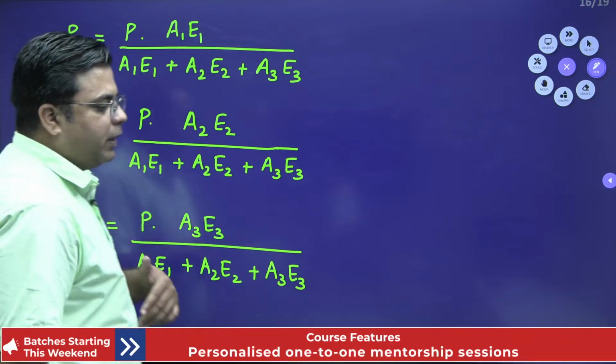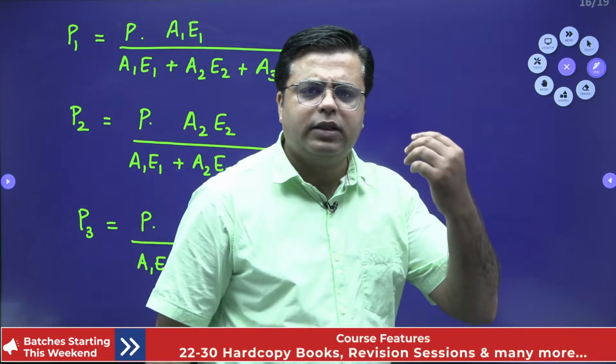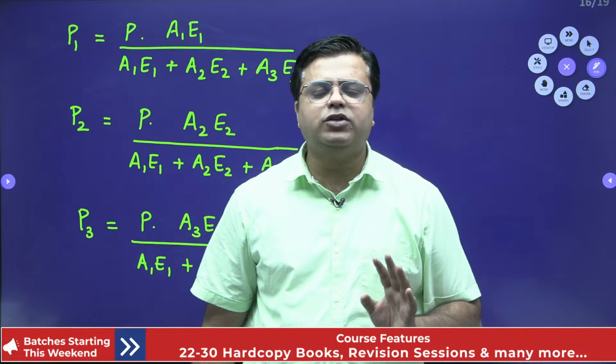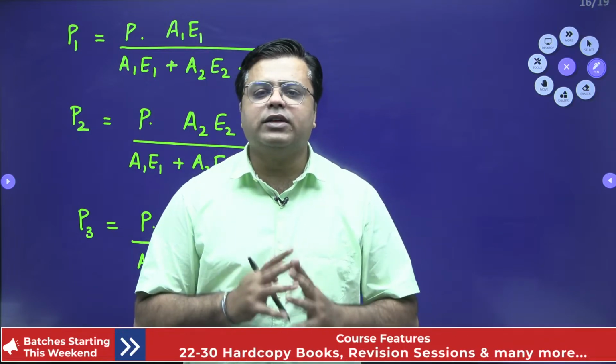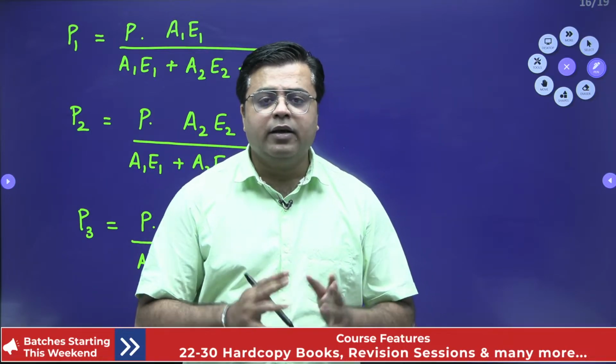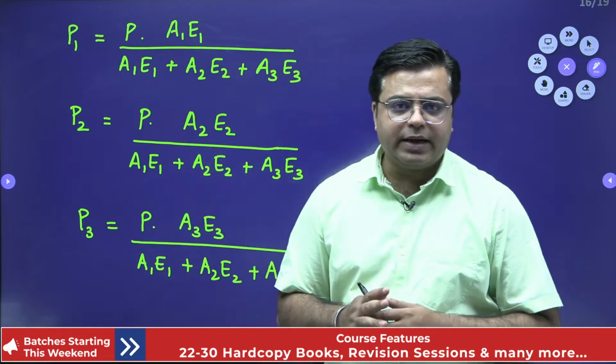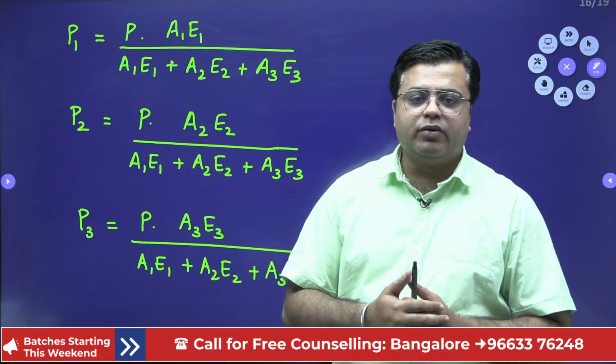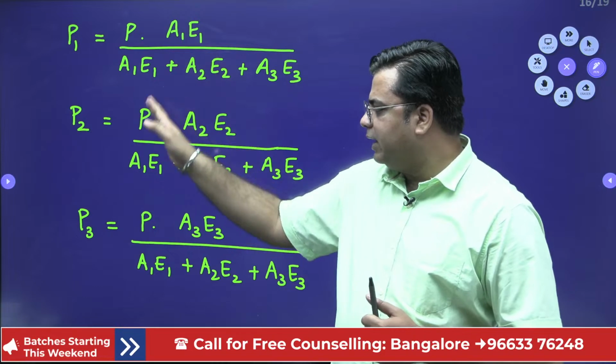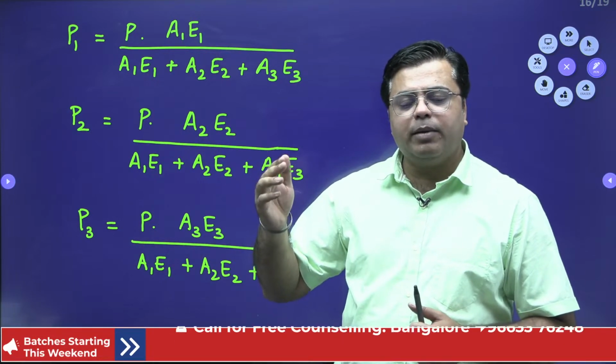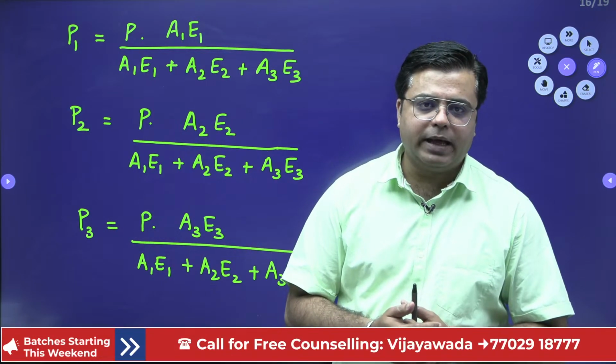And through this simple trick, you can write all the loads of the individual member without even solving the question, right? Without even doing the complicated calculation or equation solving, you can directly write the load for different members if the bars are connected in parallel, right?